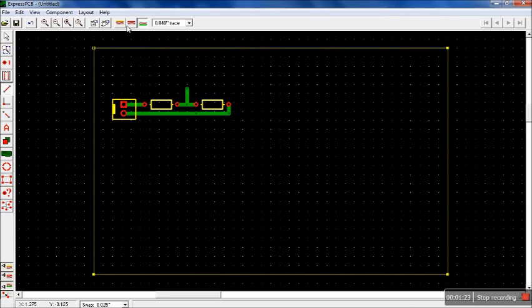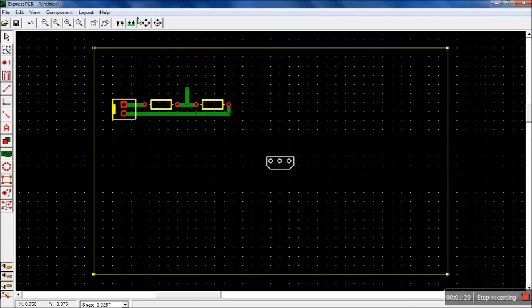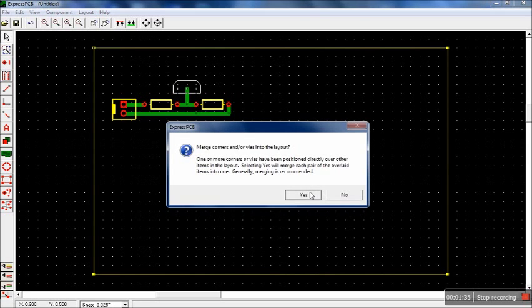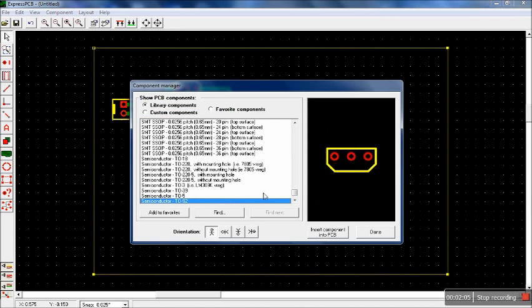Now we will connect a transistor. At the voltage divider there will be a transistor. The transistor is named TO92. The base of the transistor will be connected at the voltage divider junction. Here we will connect ground. We have to make this 45 degrees to increase the area. When we iron it, it might get cut off and we might not be able to notice that. So for that we make those cuts at 45 degrees.